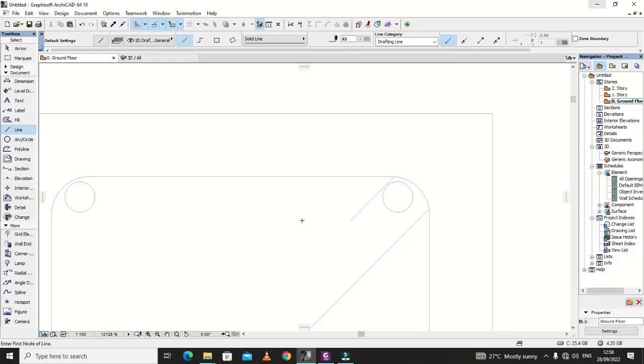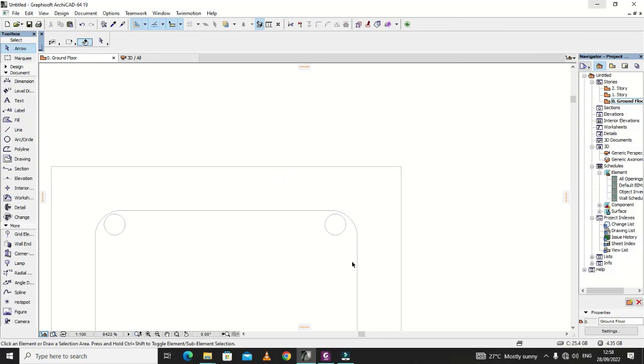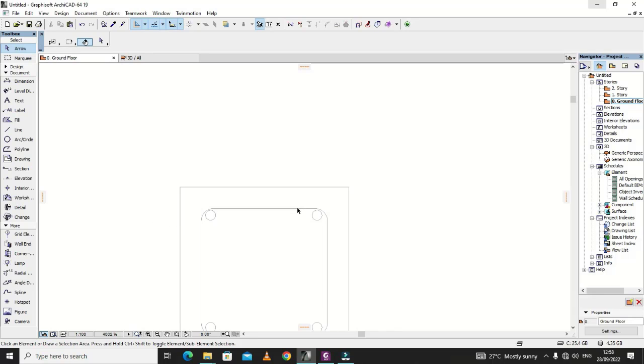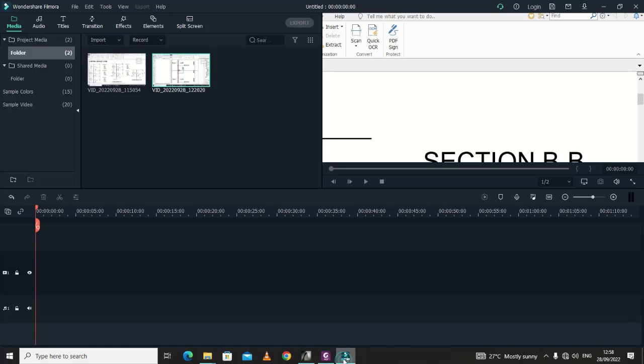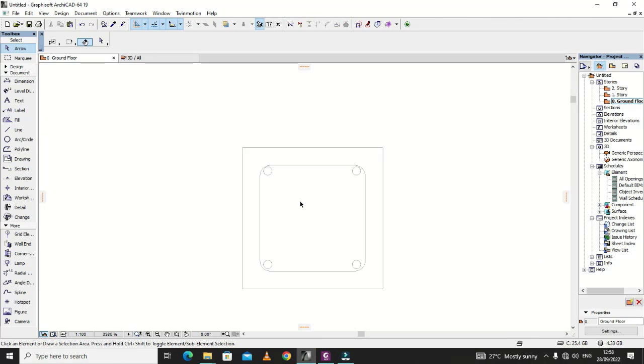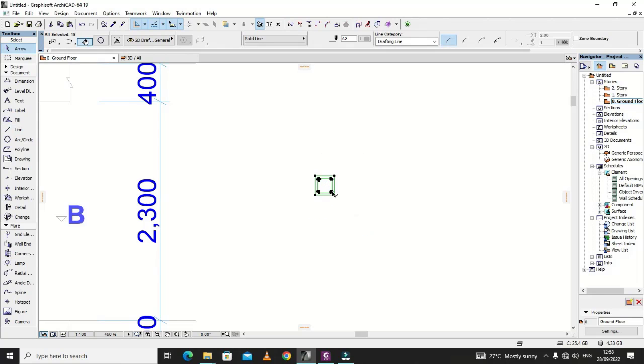Anyway, this is normally 100. That's too big. So or alternatively, let's just leave this part, because sometimes they use the 90 degrees bend, and there's also the 135 degrees bend. So let's assume that the decision of whether to use the legs in the 90 degree bend or the other bend will depend on what the foreman is going to choose. So let's leave it like this, or we can still introduce, but let's just show a small distance, maybe 20, 21. Also here, you can keep it there, that way. So that's for D12.